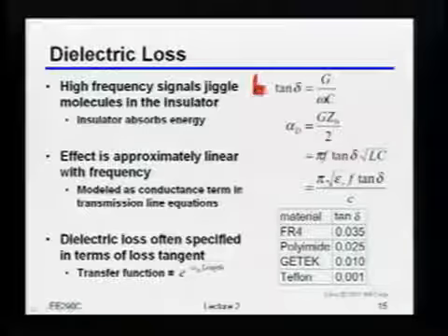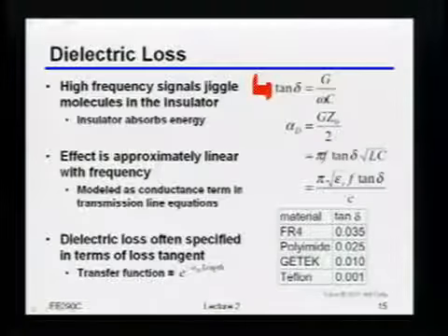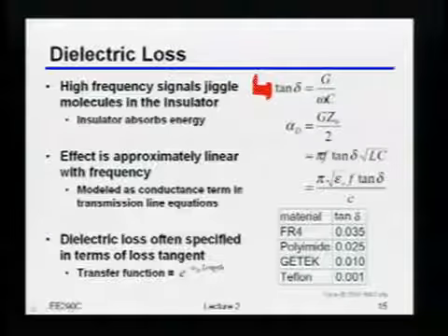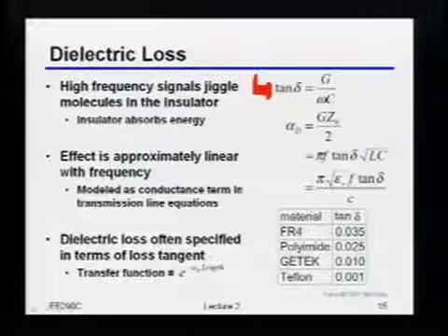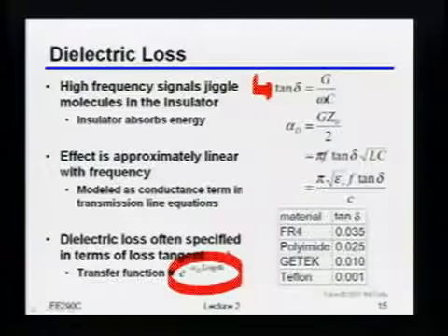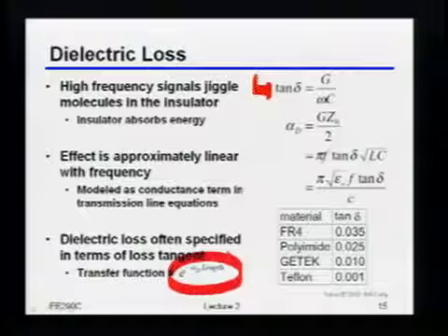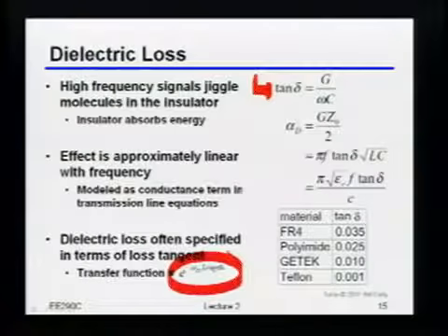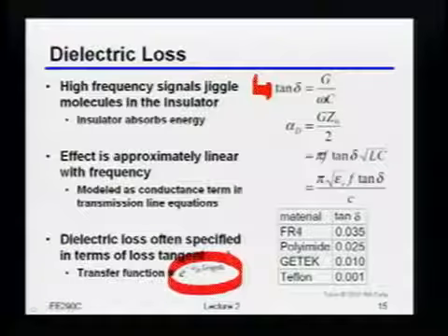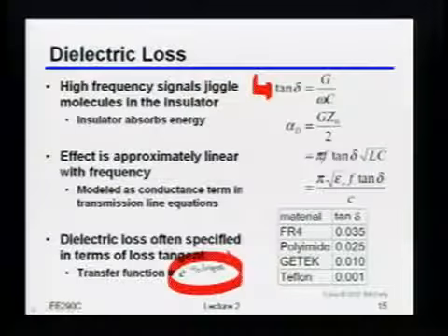It's usually modeled with what's called the tan delta, which is the loss tangent. Don't ask me why they decided to come up with that. That's just usually how they talk about it. The long story short is that it tells you that, again, your loss increases exponentially with the distance that you're traveling. Okay, because you pick up more and more of this dielectric material that you have to heat up as your signal is propagating.